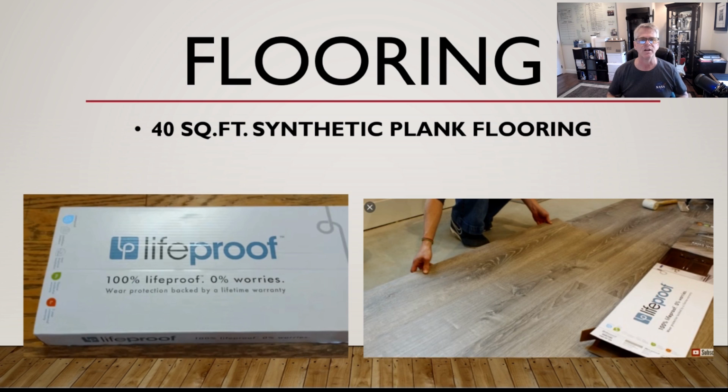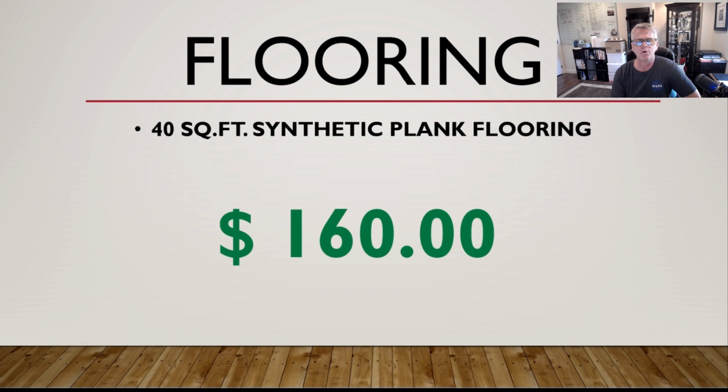It's their brand of synthetic plank flooring. I'm using it in 95% or better of all my basements and basement bathrooms. The stuff is, just like the name says, life proof, water resistant, mold resistant. It's a floating floor, it conforms to uneven concrete floors. I mean, the stuff was just made for basements. It's pet proof, kid proof, stain proof. That's what we're using. $160 for 40 square feet of it.